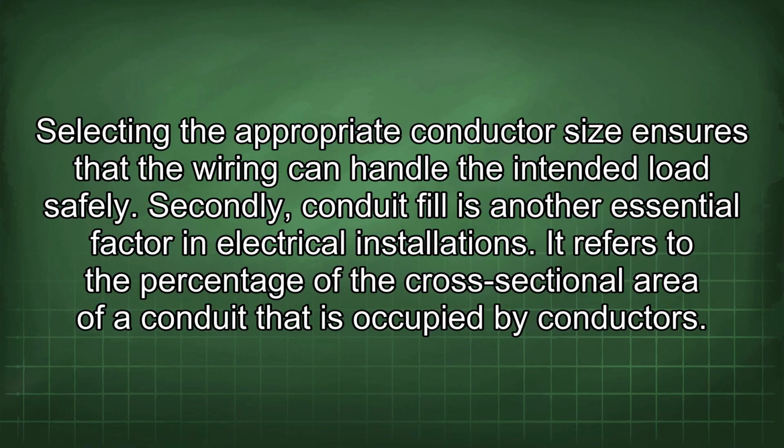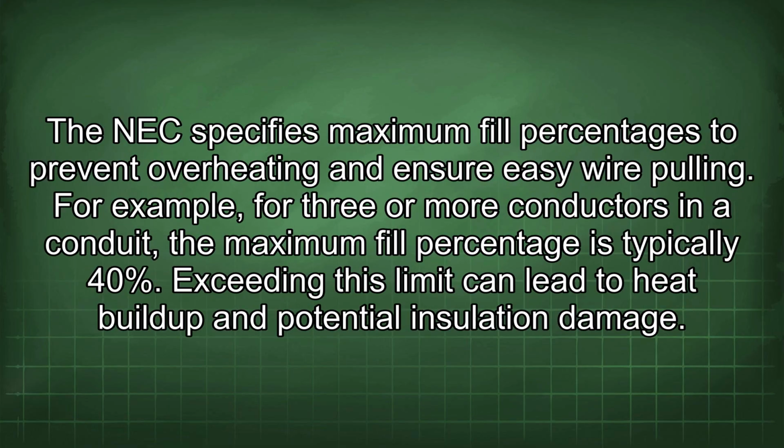Secondly, conduit fill is another essential factor in electrical installations. It refers to the percentage of the cross-sectional area of a conduit that is occupied by conductors. The NEC specifies maximum fill percentages to prevent overheating and ensure easy wire pulling. For example, for 3 or more conductors in a conduit, the maximum fill percentage is typically 40%. Exceeding this limit can lead to heat buildup and potential insulation damage.